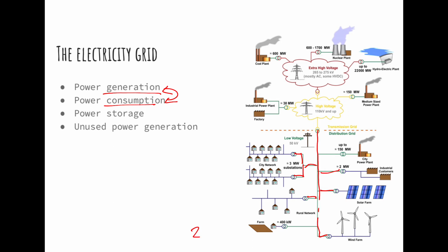Everything needs to remain at 240 volts. In summer, because there's so many solar panels on people's roofs, we're getting voltages of up to 251 volts, which is getting dangerously high for the components of our electrical grid. It actually can't handle too much power. And so what's happening is we're having to take coal power plants offline, but then we might actually get power outages when we do that because we don't then have the power when the sun goes behind clouds or when the wind power drops off. So renewable energy sources tend to be unpredictable.